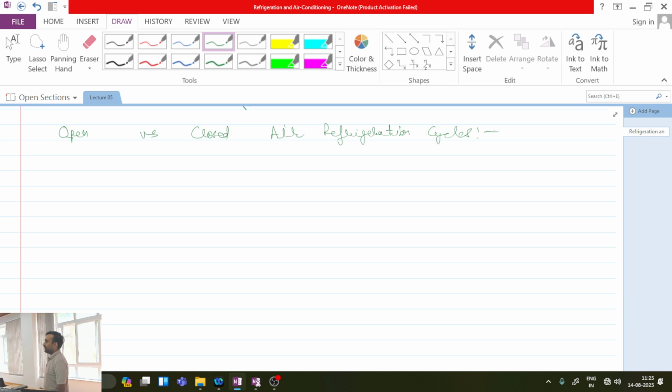So Brayton cycle, I told you, is a gas turbine engine. Okay. So in gas turbine engine, what happens? Ambient air enters the compressor, then the high pressure, high temperature air passes through a combustion chamber. Then part of this is expanded over the turbine, and the remaining part is expanded over the nozzle, and all the exhaust gases are then dumped into the atmosphere.